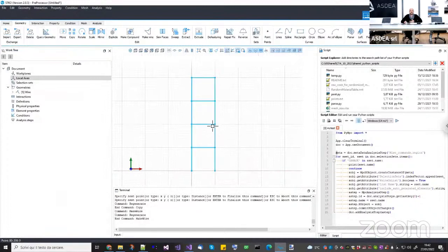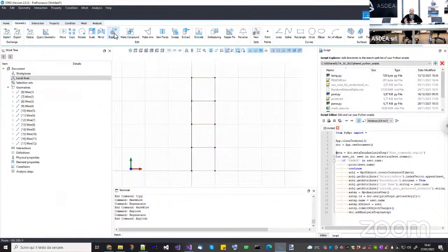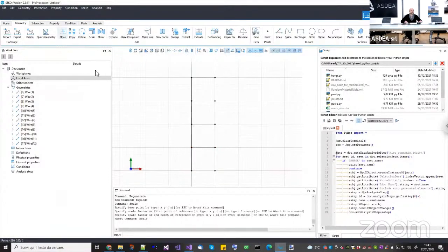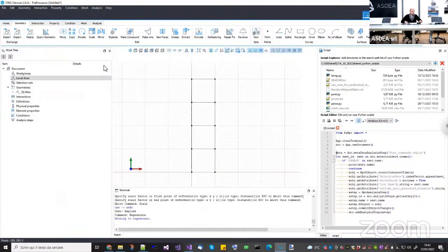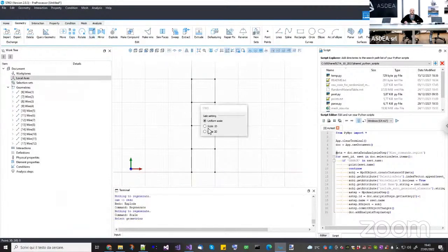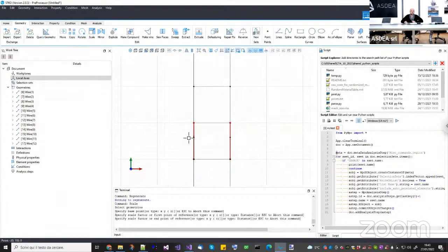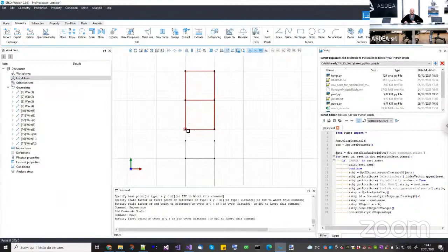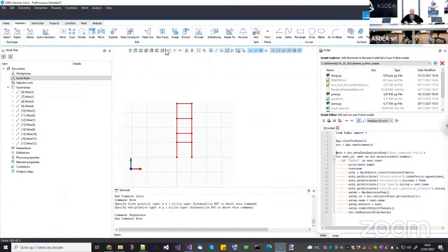Yes. Well, something that you can do is, for example, to explode everything. You will maintain the selection. So imagine that you have properties assigned to those beams. The selection will be maintained. So now, for example, you want to scale these two. Well, you can go here, scale 1D. You scale them of this particular factor, whatever it is. Let me do it again. Scale 1D, right click, select the base, select the top, and then we go down a little bit. Perfect. So this is my new height. I select all of them, I move them back, and then I perform once again the make wire.